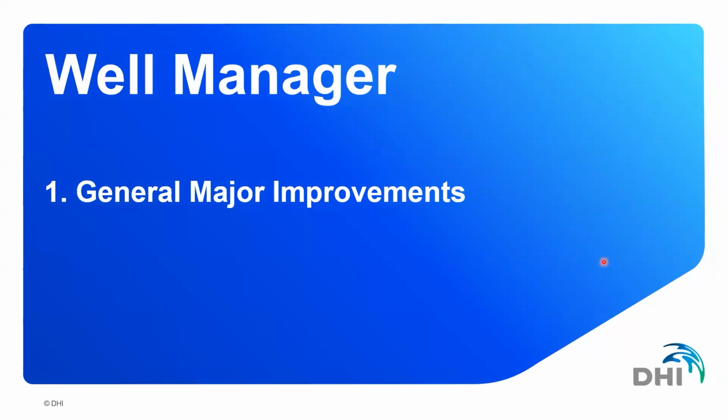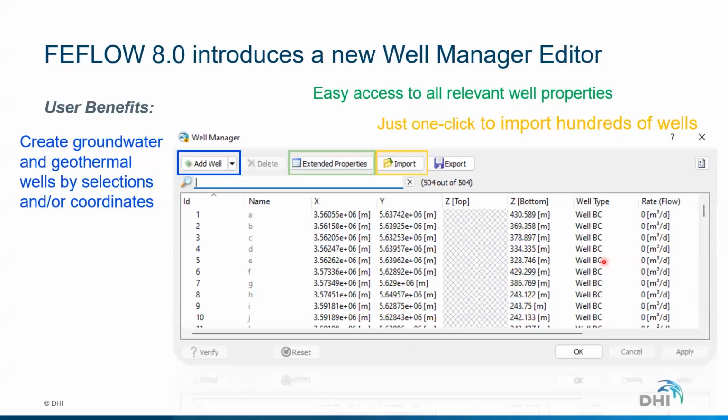Well Manager: we have a lot of major improvements on the Well Manager. The Well Manager is a very popular tool which was introduced initially with FEFLOW version 8.0. It has the ability to create any type of well BC, multi-layer well, or borehole heat exchanger from the same location.